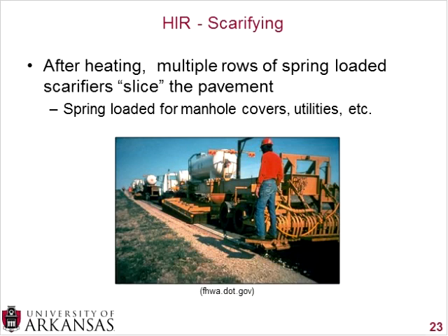After you have heated, here's a picture of scarifying the pavement. What happens is there are multiple rows of spring-loaded scarifiers, and they literally slice through the pavement. If you're cutting a cake with frosting on top, you drag that knife just across the surface and it scarifies that frosting. That's what we're doing with the pavement here. And they are spring-loaded, so you'll see in some application pictures upcoming, but manhole covers and utilities, these basically just bounce over those. So you're able to heat those utility covers and then just scarify around the utility covers.